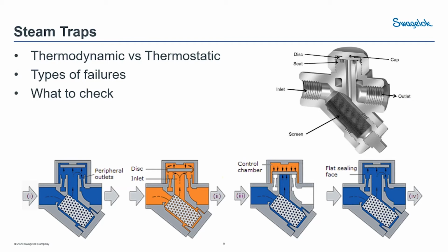We're just getting hot steam blowing through and contacting, so you're going to waste a lot of energy. Or the other thing that's possible is they just don't open at all. They're completely locked up. So what to check and what to look for on those.